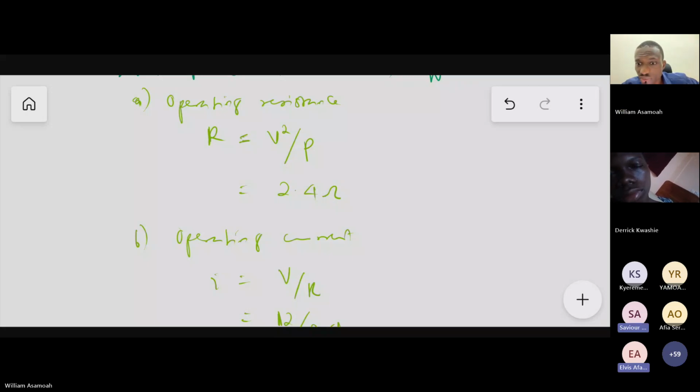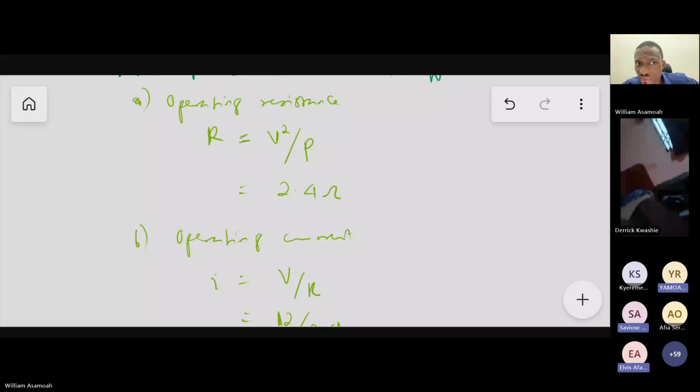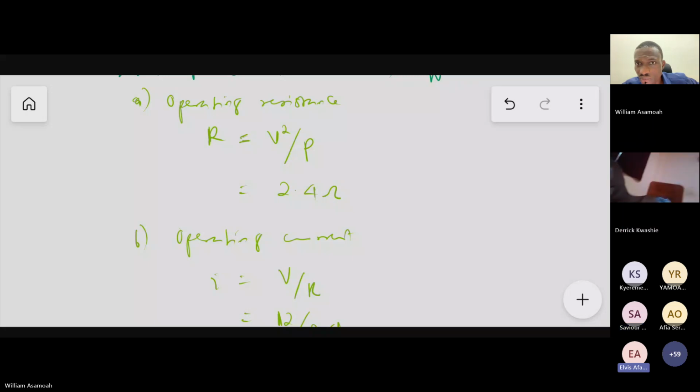Okay, so at the beginning the tungsten filament is at room temperature, and when the inrush current is coming, the resistance of it is relatively lower because it is cold at that moment. Now it experiences a warm-up process where the electric current is converted into heat. As the temperature increases, of course, there will be vibrations between the atoms of the tungsten, and this would impede the flow of the conducting electrons.